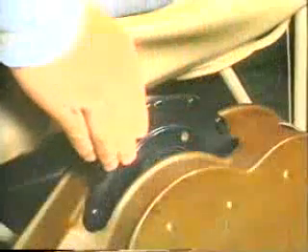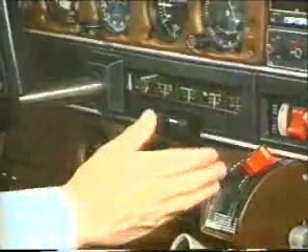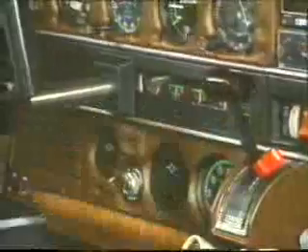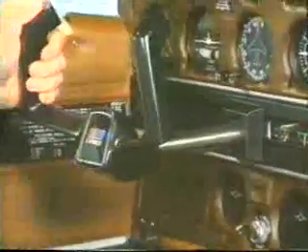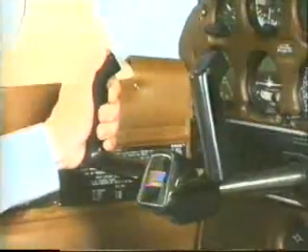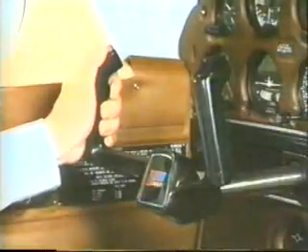You can experience this by trimming your airplane for cruise flight. Then, with one hand on the control wheel, increase power and maintain level flight. The control pressures tell you that the airplane wants to climb. This confirms that an increase in velocity causes an increase in lift at a given angle of attack.